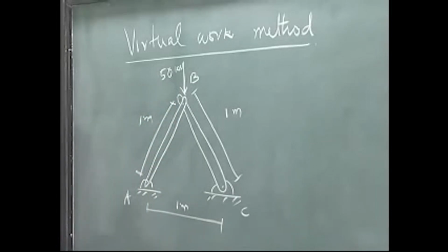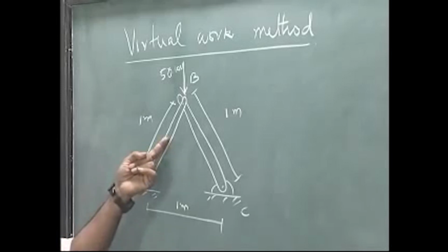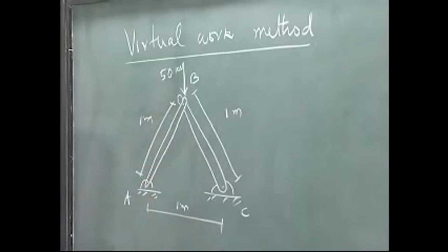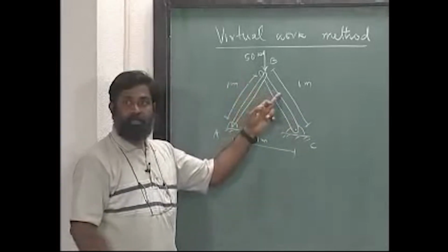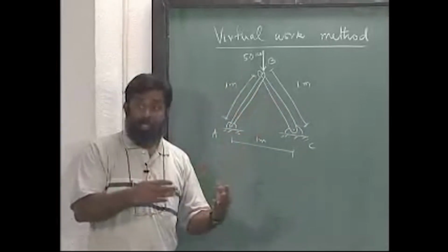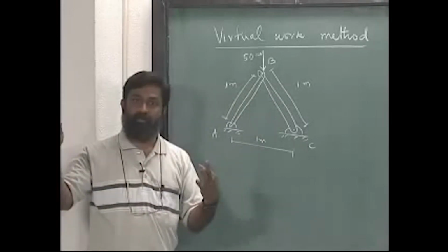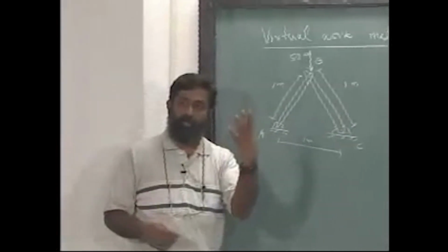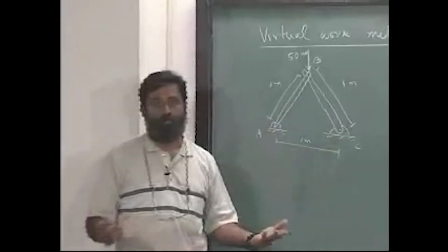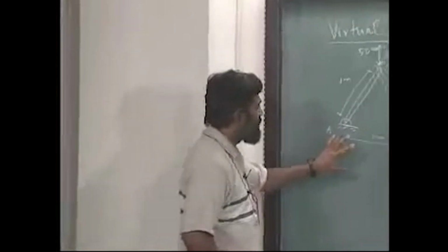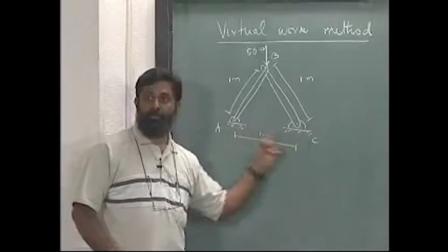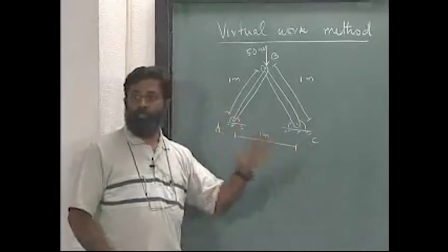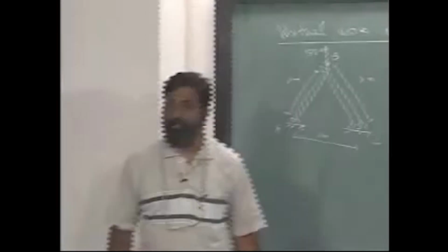That is not very difficult to understand. I can fix one of these and then see whether the other bar is moving; the other bar can rotate about this particular bar, which means there is 1 degree of freedom. If there is 1 degree of freedom internally here, I can generate 3 equations for the rigid body plus 1 using the 1 degree of freedom, which means 4 equations can be formed and we have 4 unknowns, so we can solve for them. In that sense this is a determinate structure, meaning I can always find out the unknowns using just purely equations of equilibrium.